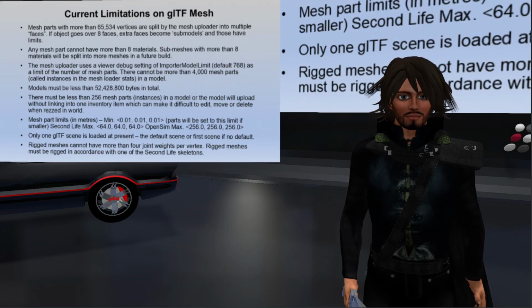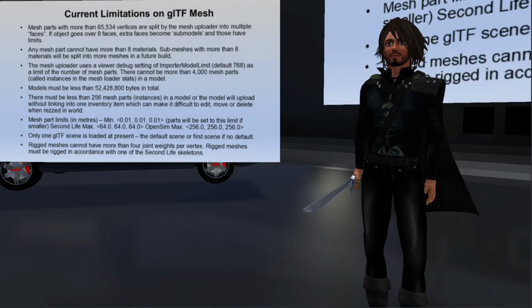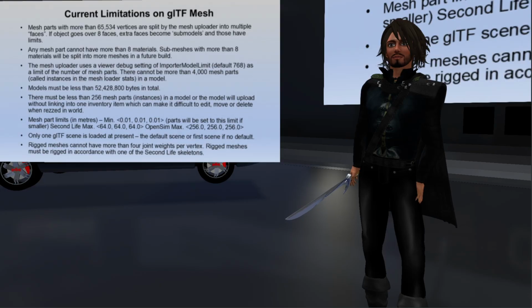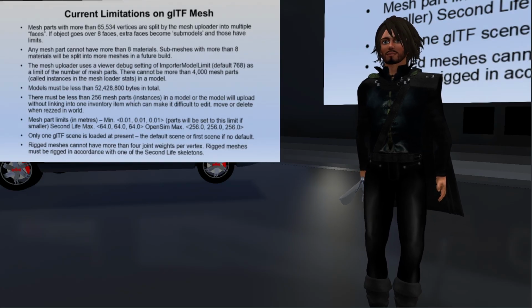So what you can do if you have problems, and this is my experience, is simply say that you want the bounding box physics, which gives you a very crude, cube-like structure around it, which isn't really suitable for things like buildings where you're walking through doors, or like the oil rig model that we have, where you really have to go down individual stairs.